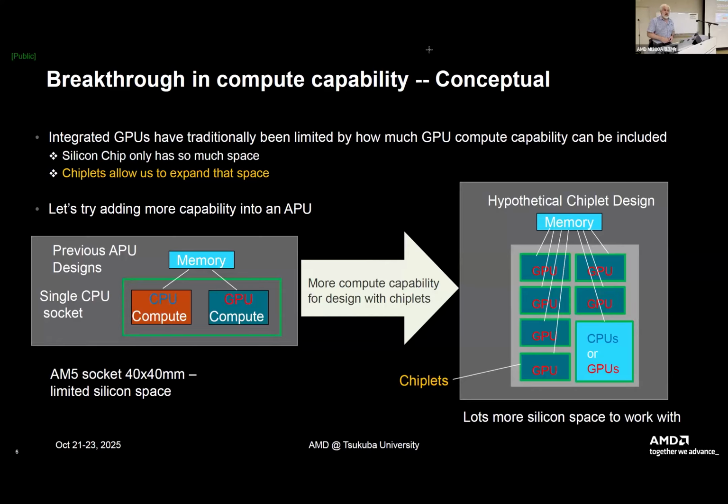A Knights Landing from Intel, they had a lot of yield problems because it was such a big chip. And after they sent out the first systems, they sold all the Knights Landing chips that didn't meet specifications at very low prices. But because we're using chiplets, we take the chiplets that pass the testing and put them on the board, we can get much higher yields.